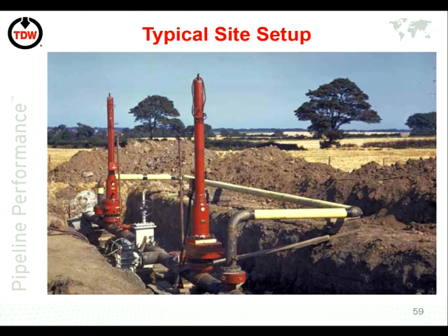Again, the times are changing and the expectation is that you have double block. There are two variations you can have on this. One is you can have two stopples, so you have an extra fitting and two stopple fittings in there. Or you can have what's called a stopple train, which is a plugging head with two sealing elements on it, and that will give you the double block requirement. So yes, you're right, most operations now require double block, and certainly in an offshore setup you would need double block.